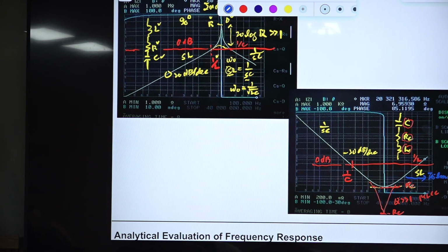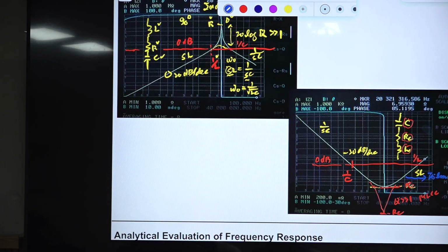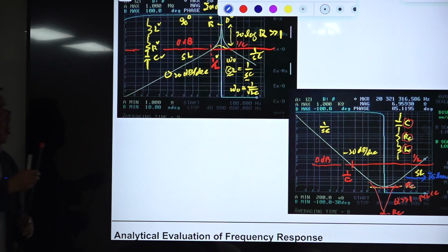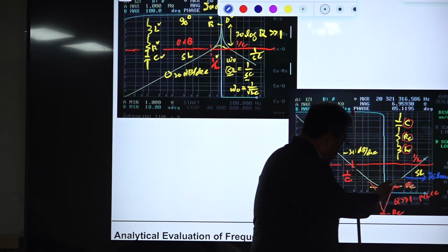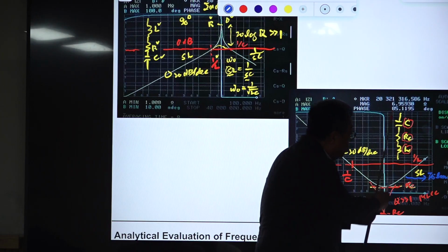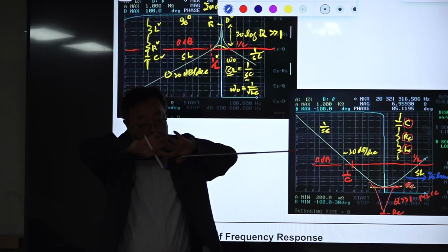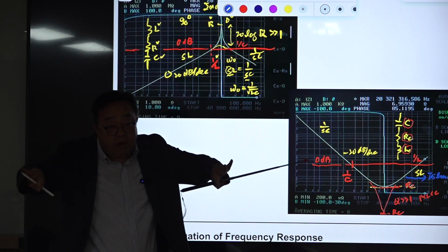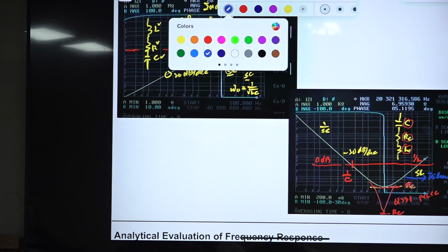All right, the cheapest one is the electrolytic capacitor, which has a plus minus polarity. In that case, Q is very small, less than 0.5. So here we have a double pole, a second order pole. This is a double pole with very high Q and medium Q. If Q becomes less than 0.5, the double pole splits into two separate poles. So for this one, the cheapest capacitor,